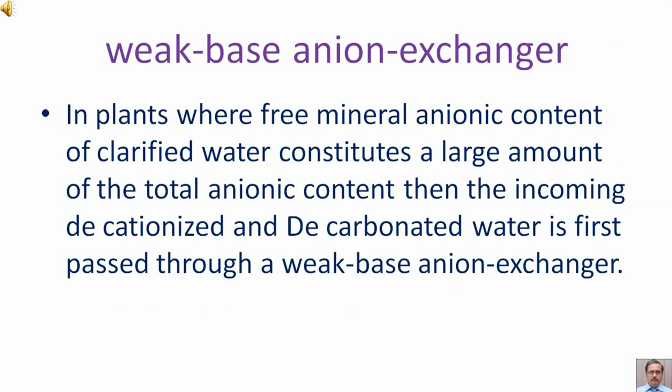In plants where free mineral and ionic content of clarified water constitutes a large amount of the total anionic content, then the incoming decationized and decarbonated water is first passed through a weak base anion exchanger.